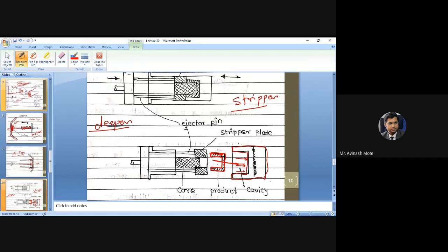So here is the stripper mechanism, this core. This core is holding this stripper. This core is pushing. Look, from this side there is a pushing mechanism. This will push this core. This core will push this stripper, and the same way as the spring back mechanism, they will pull back the stripper when the component is stripped out of the mold cavity.